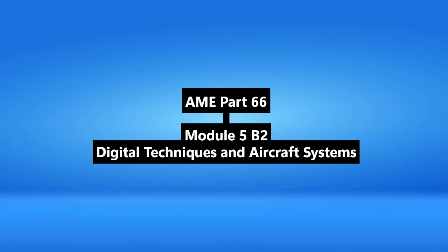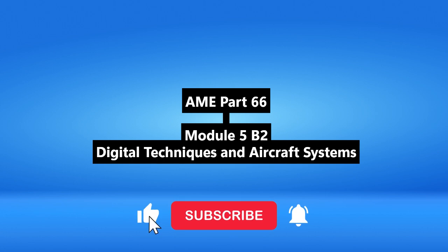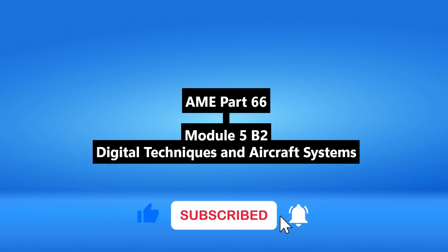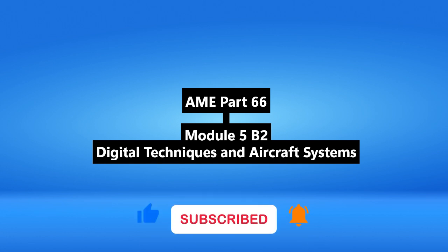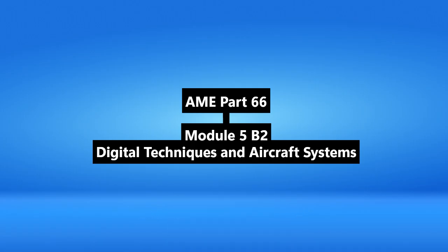Okay, clear. And just quickly, the module mentions DC and AC analog signals. The difference. For our purposes, think DC, direct current, as unipolar. It varies, but always stays either positive or negative relative to a zero reference, like a slightly fluctuating battery voltage. Okay. AC, alternating current, is usually bipolar. It swings both positive and negative around that reference point, like a sine wave. Different sensors, different systems use one or the other. Got it. Okay, that lays the groundwork.